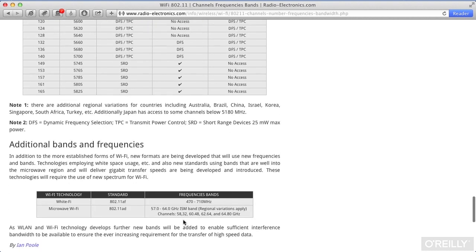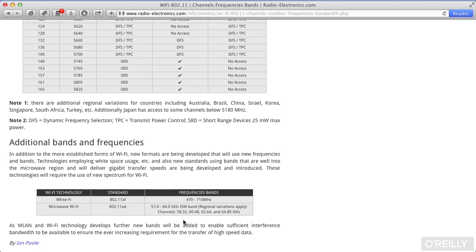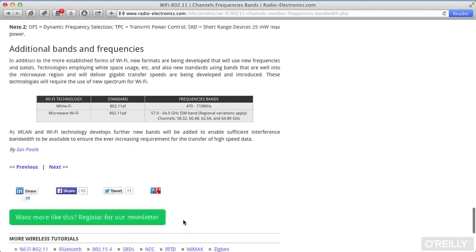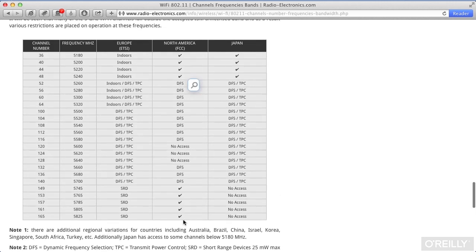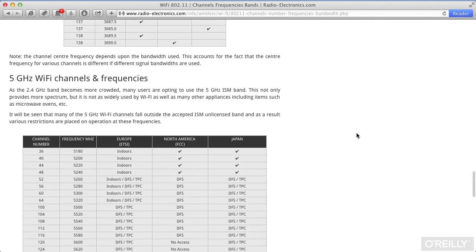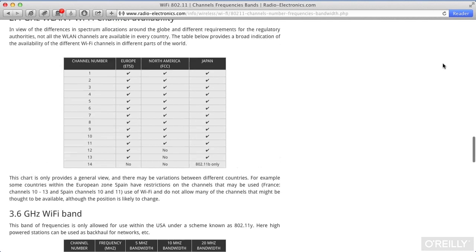So there are a couple of different frequency ranges, and as I said, different consumer electronics will make use of some of those frequency ranges or somewhere near them. A cordless phone or a microwave oven are really common ones, as well as other devices operating somewhere near that same frequency. You could end up seeing spikes into the same range where you're trying to operate your Wi-Fi network, and you could see degraded performance.